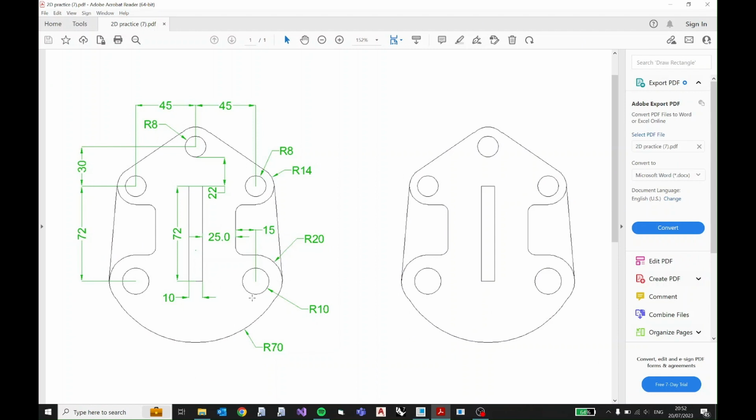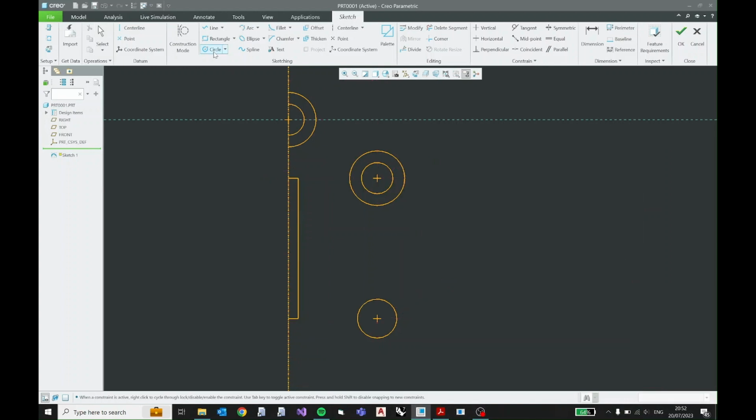I'm not gonna be making just an arc. I'm gonna make a complete circle, and in the end I'm gonna be deleting the rest of the segments that we don't need, similar to what we're doing over here. So the radius of this arc is 20. I'm gonna make a circle of 20 units. Over here, make it radius, and then select 20. Perfect.